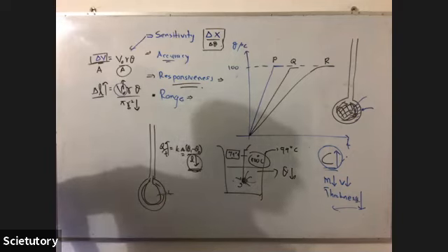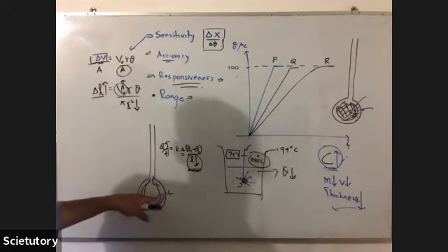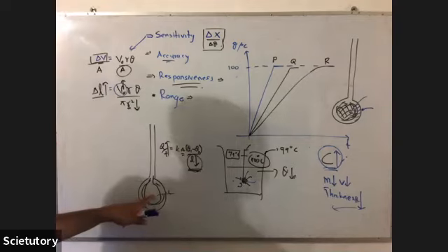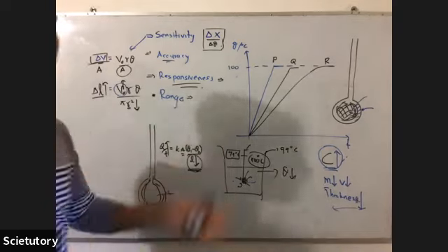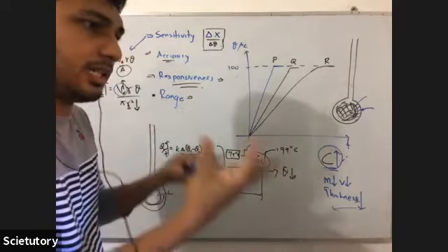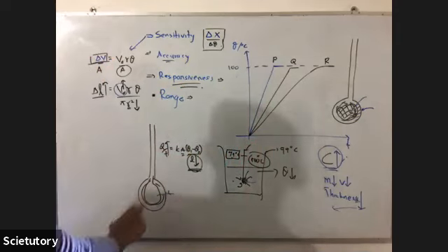So the responsiveness is determined by the thickness of the wall and also the amount of mercury used. If you use a higher amount of mercury, the mercury as a whole should get heated to that particular temperature, no? So it takes time if you have more mercury.